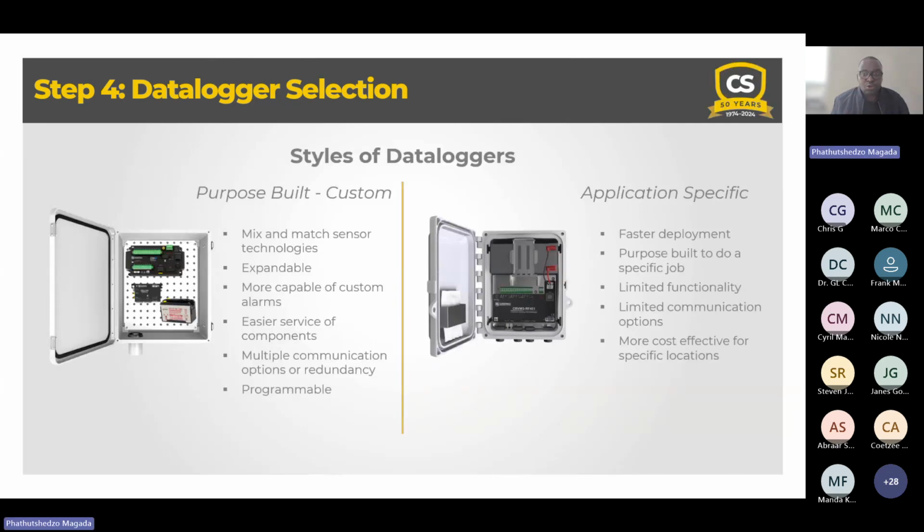So if you look on your right, you have the CRVW3. This is designed with 3 sensor inputs, and it's suitable for small geotechnical projects. This is mainly applied where sensors are grouped into 3. So you can use this data logger in a situation where you have multiple sensors, and those sensors are mixed, and maybe at some point you will need to expand your sensors.